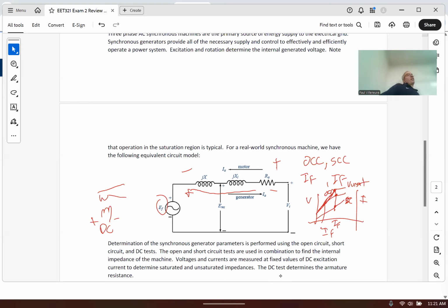There's a device out in industry called a phase angle regulator. Kind of interesting, right? Why would you want to regulate, or control, the phase angle? Because you can control power flow. If you have a way of controlling phase angle, you can do a big amount of control on the real power flow through a device.